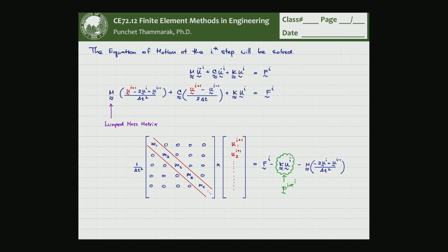All right. Now, still in the big picture of this, why is it beautiful? You still wonder, I know. You look at these formulations. The right hand side are all known, so it is just one vector. All right, easy. The left hand side, due to the use of the lumped mass matrix, makes the diagonal the only non-zero terms, and the off-diagonal terms are all zero. So what kind of equation do you have over here?